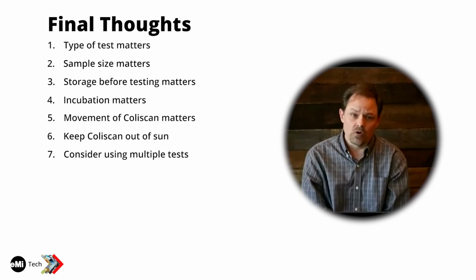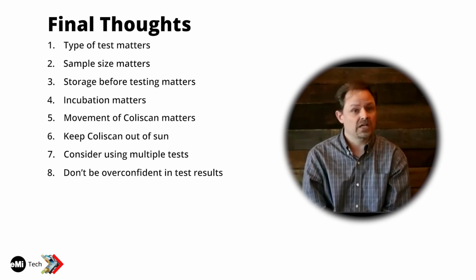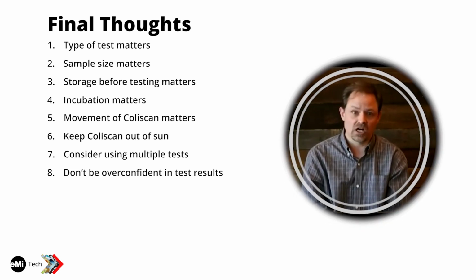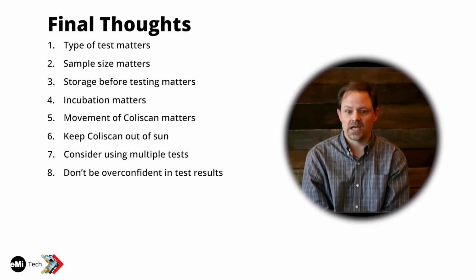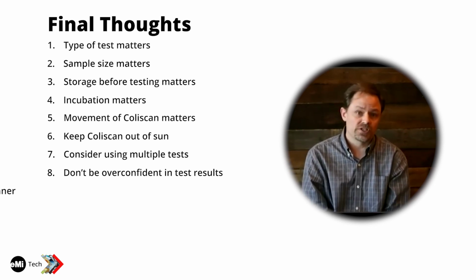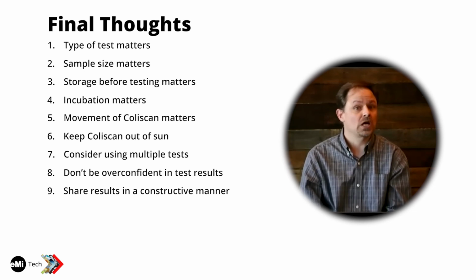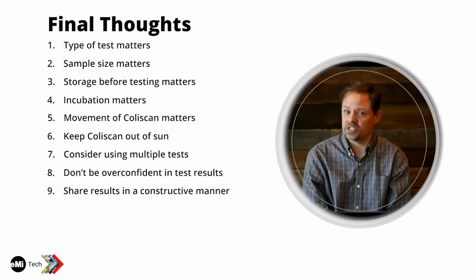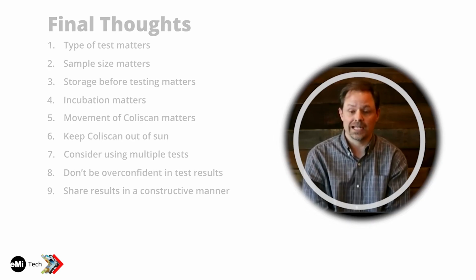Also, don't be overconfident in your results. Recognize false positives and negatives do happen. There's limits on what even the presence of coliform or E. coli tells us. And then finally, I think it's really important to share your results in a constructive manner, because it can be overwhelming and confusing to a ministry, because they're not familiar with all the limitations of the results when they get it.